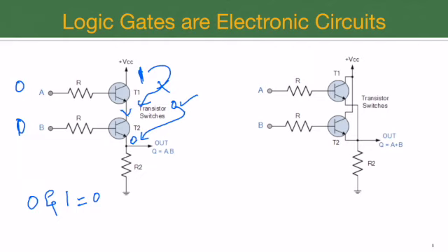So this is the electronic circuit for the AND logic gate. Similarly, the circuit shown over here is the circuit for the OR operation. If you can follow the way I showed the input, the key here is that the output is a combination of the value over here, whatever is produced on this line, and the value produced on this line. So let's very quickly have a look at an input of 1 and 0 and see what result we get. We always have a value 1 over here because it is connected to the power source. If I apply the value of 1 over here, this 1 will get transferred at this point. So I will get a result of 1.